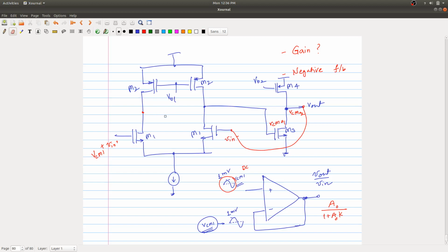So what I am suggesting, rather than doing this, just to have the same DC condition here, where VCMI and VCMI both are equal, what I can do, so unfortunately this is not given in any book, but all the industry people are doing this. So let's assume that this is fully differential, with the same thing on the other side, it's also available. So to get the same DC potential, there is a trick: let's add one inductor,